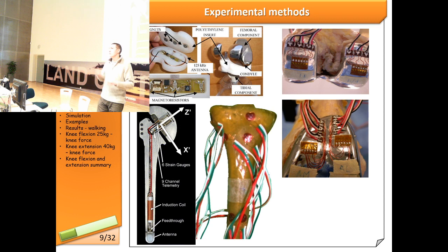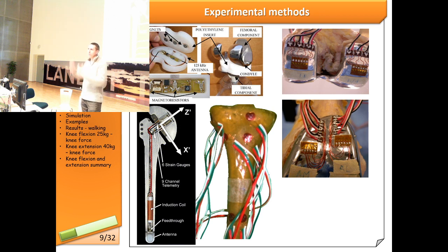Then, knowing those stresses at the few points where you can actually install the sensors, because if you install, let's say, 200 sensors on that bone, even the cables' weight will affect the results because they will be pulling everything down. So you should have just some number of points that do not affect the reading, and from those you compare with the finite element model, fine-tune it, and get some properties of the material or the modeling technique that you're using for modeling the body.